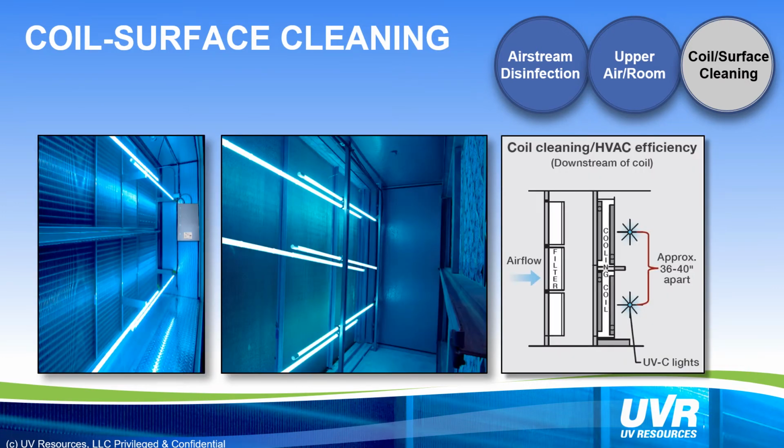While not explicitly designed for airstream disinfection, an HVAC surface irradiation system can also provide first-pass inactivation ratios of airborne pathogens of up to 80%, along with the primary benefits of restored cleanliness, improved heat exchange efficiency, and lower energy use. And, as pictured here, a coil maintenance application requires less UV energy than on-the-fly applications due to the extended residence time. In other words, unlike a microbe in a moving airstream, the cooling coil is stationary and absorbs UVC energy around the clock.